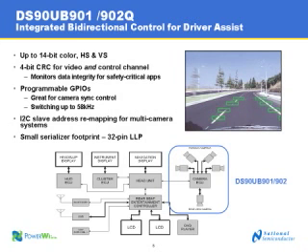The I2C slave address remapping allows the system to have multiple cameras attached that could all have the same I2C address. This avoids the problem of having a single address for all the cameras. It allows a remapping to a unique identifier so that the host system can independently address each one of these cameras, even though they have the same address.